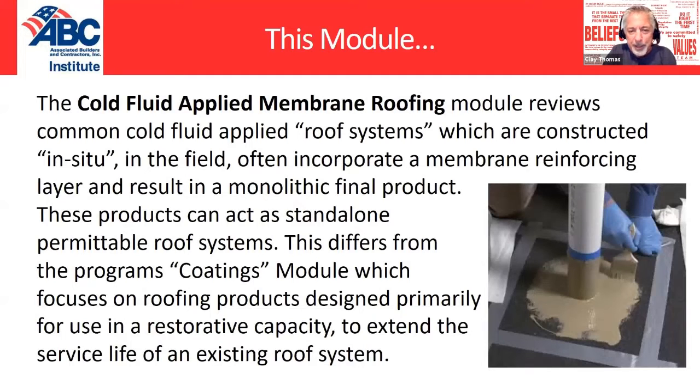Okay, so they're unique in that you build them in the field. So when we build sheet product in the factory, it's a very controlled environment. So really the seams are the only main places that we have a problem at the end of the day. So when you build these systems in the field, you're subject to environmental conditions. So one of the key applications and installation considerations with these systems are the environmental conditions that you're putting them down with on a daily basis. And if you're going to have a product failure, that's probably one of the main places that you're going to have it.